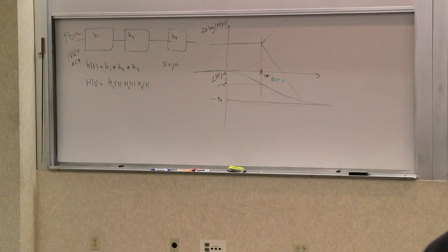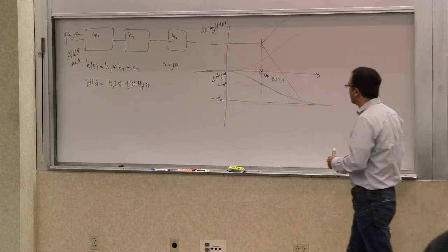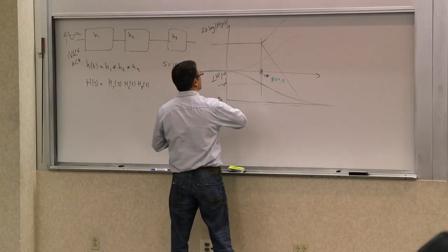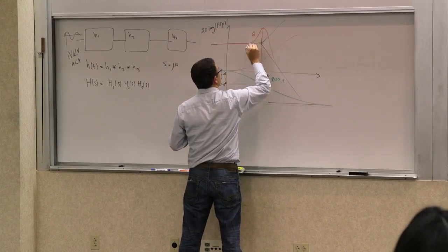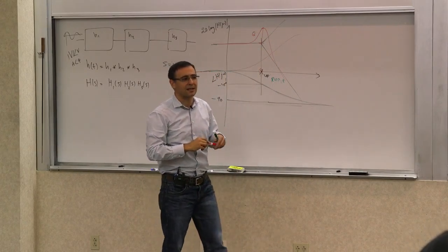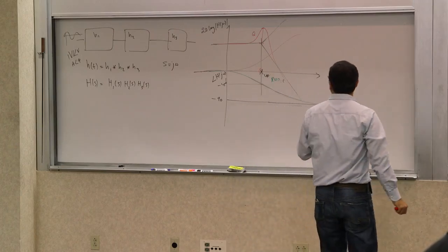And then what else did we do? So we looked at those. We also saw that if there's a second order system, there would be peaking. The amount of peaking is proportional to the quality factor. So if you have a second order system, you will have peaking, and this would be roughly Q happening at omega n. And we took that and used it.